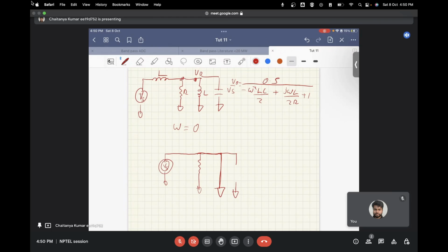So what is the problem that we are facing here is that we cannot outright say that the impedance is a short circuit. The impedance will be close to short circuit, but then we need to see that the source impedance is also almost zero. So the impedance over here is also almost going to zero. And if this impedance is very small, then this resistor can be neglected.